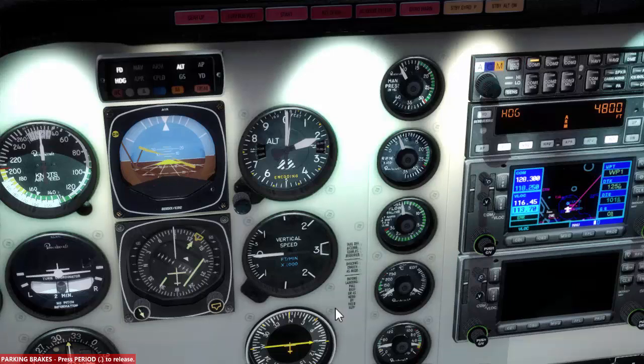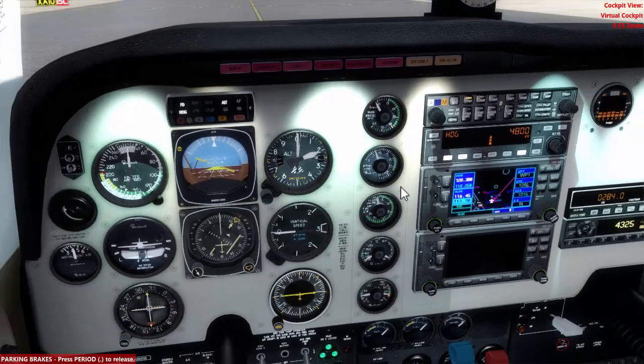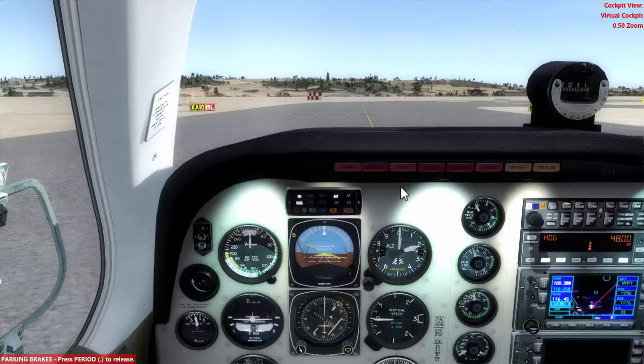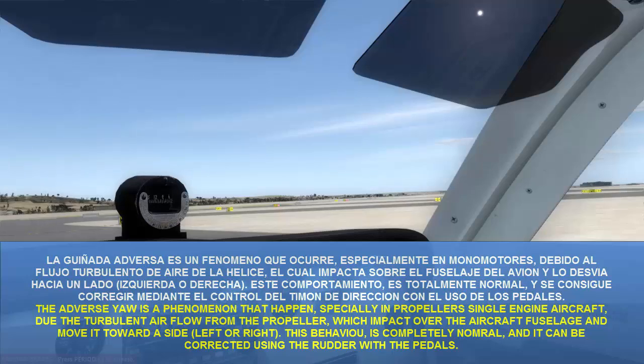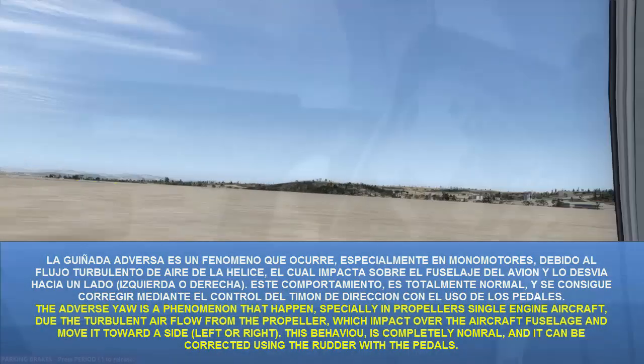So we will take off with ramp 129, and then when reaching a certain distance from the Barajas VOR, we will follow the radial 125, okay, and we will do that step by step following the standard instrumental departure chart, and I will explain that to you little by little.